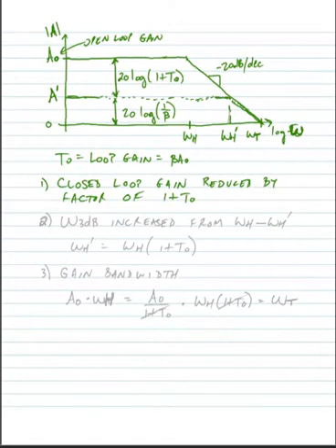Now, why do we do this? Well, we can control the feedback. It's a ratio of resistances. It's much harder to control very precisely the very large gain, A sub 0. So what we do is we trade off having a very, very large but uncontrolled gain for stability and a very well-controlled gain.